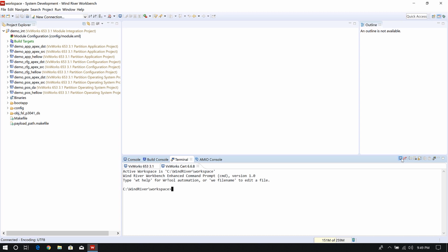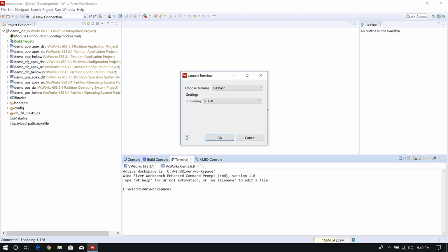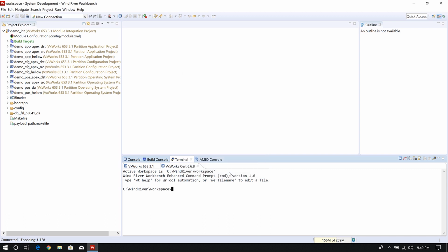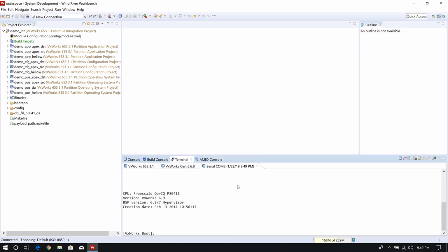We've connected a Freescale P3041DS to our host with an Ethernet cable and a serial connection through a USB to RS-232 converter. Workbench helpfully comes with a serial terminal, which we'll configure to communicate using that converter at COM3 at 115 kilobits per second, N81. When we turn the board on, we can see its initial messages from the boot app, and we could display its boot settings. I've already configured networking on the board and the host to use a private Class C subnet.